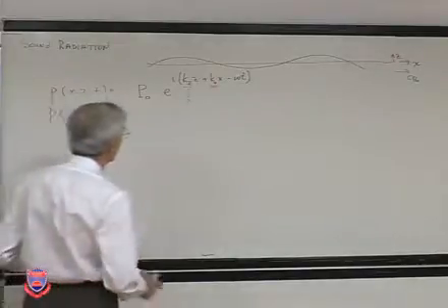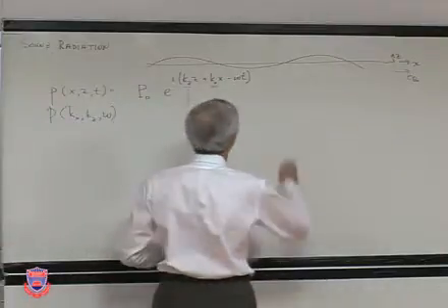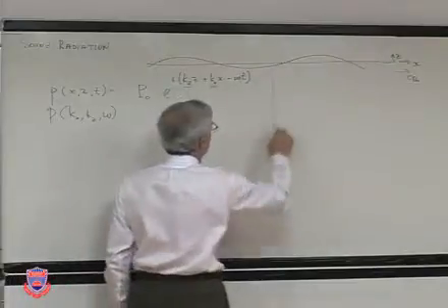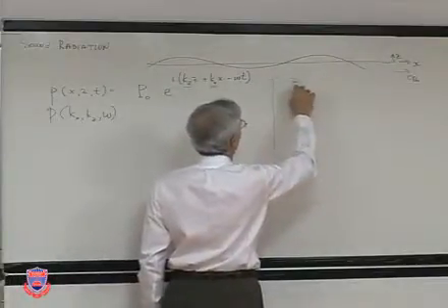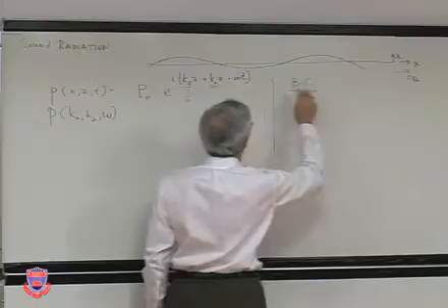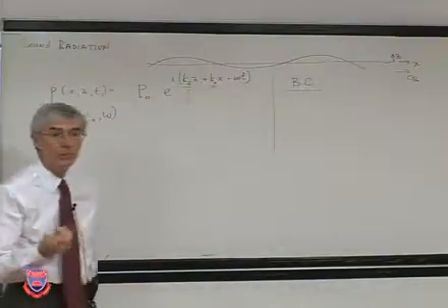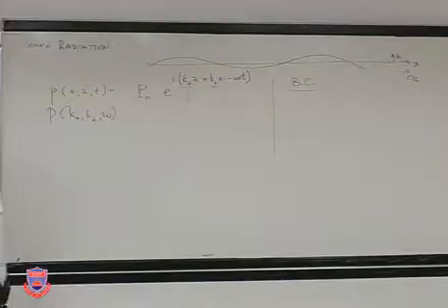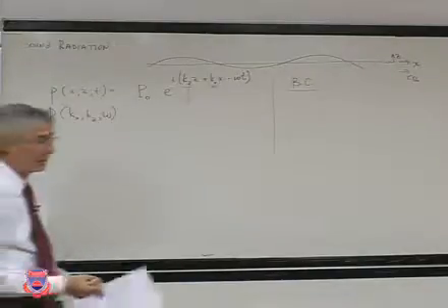So the next thing we did here was determine the amplitudes. One thing we do is use a boundary condition. And the boundary condition is the normal velocity at the surface of the plate should be equal to the plate's velocity at that point.